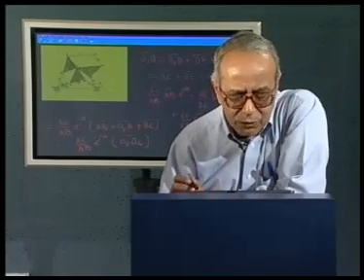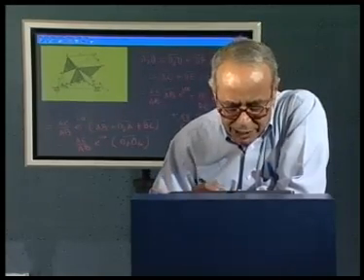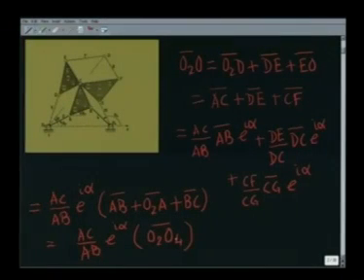As the mechanism moves, all the vectors change, but O2O4 never changes, because O2 is a fixed point and O4 is a fixed point. So, the vector O2O4 is always on our x-axis without changing its length. Neither the length AC nor the length AB changes, because those are rigid link lengths. Same is true for this angle alpha, which is the angle alpha of this ternary link. Consequently, as the linkage moves, the vector O2O never changes, which means the point O never moves in this mechanism.